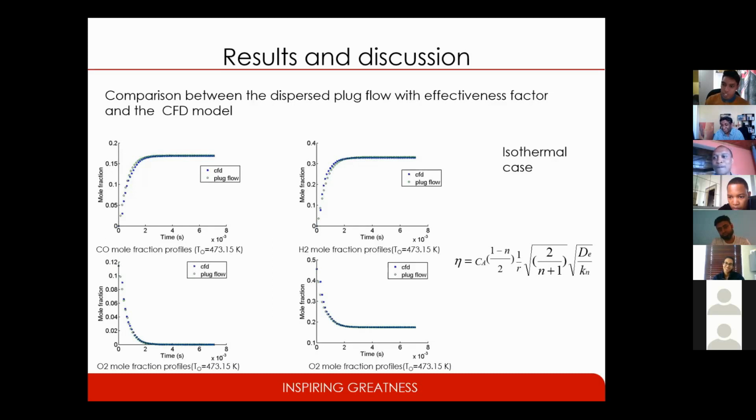Prof, if I can just chime in there, I hope Mopeli doesn't mind. I know it's true because I got marked down for that in design because the trickle bed reactor, we had a similar situation. The optimum length was about 4 point something meters, but most of the reaction was happening within less than a meter. And they asked us why is it 4 meters? The maths showed that was the optimum length and we couldn't explain why. After we got marked down, they told us that that's why, because of the migration of the zone, because towards the beginning, you'd have more products eventually than reactants. So the reverse reaction would be promoted. If only I knew that before they asked me the question.